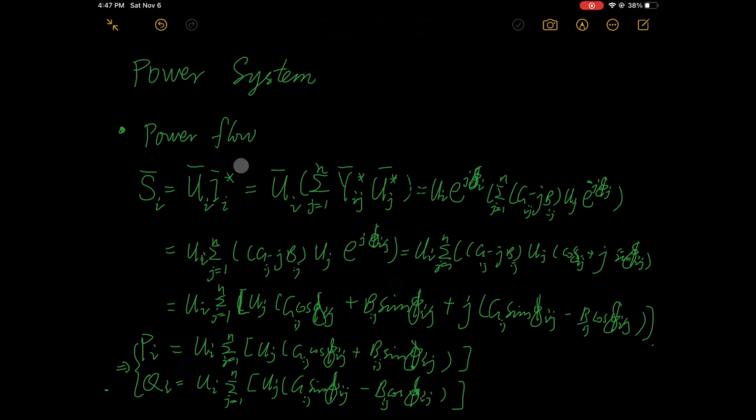Today I'd like to talk about forming and solving power flow equations. We use these equations a lot, active power P and reactive power Q injection at node I. But there's no need to memorize anything. Just start with calculating the complex power S at node I and do the following steps.